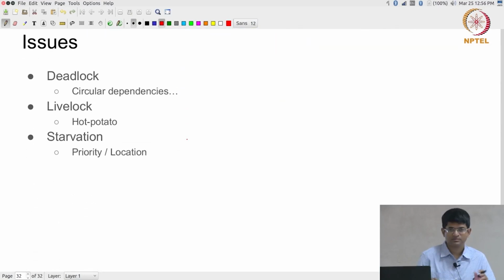So the last thing is some issues that come up in the context of understanding this. One of them is called deadlock. I told you already about deadlock, two things coming together at the same time. Usually that happens also in the case of circular dependencies. Let's say 4 units, or the ideal situation is 2 units trying to talk to each other. This is trying to send some data, the other one is trying to send some data back. This has already sent part of the data and filled up the buffer over here, so it can't continue sending the data, it is still stuck over here. B is not able to send the data because once again it is waiting for something that is coming from A. So deadlock can happen in that kind of situation. It can even happen in the case of the flit based routing. There are examples where you can show that it can lead to deadlock if you are not careful about how you do it.